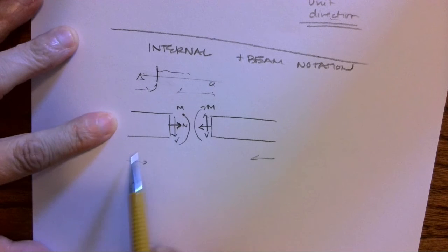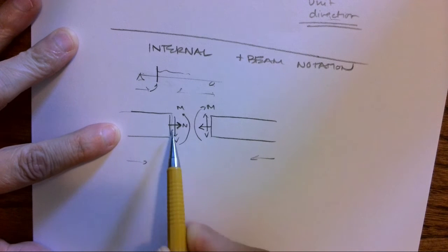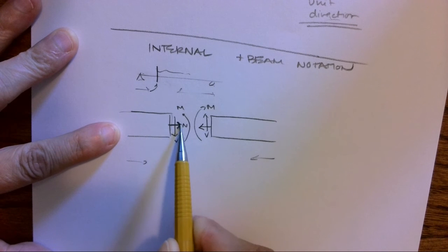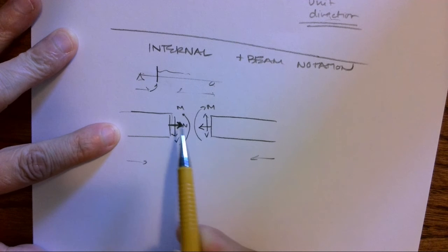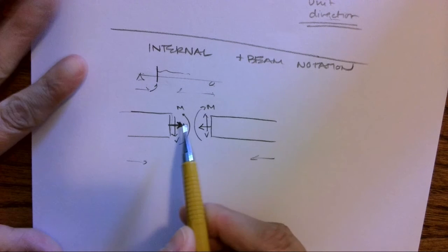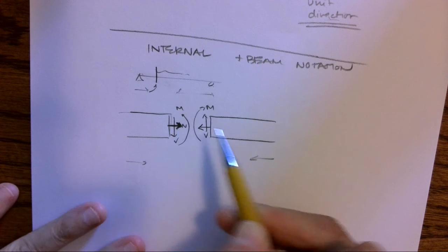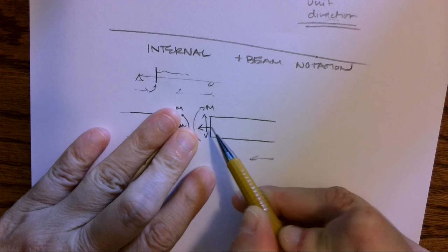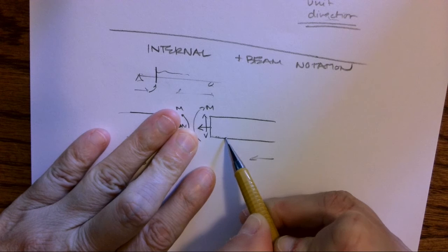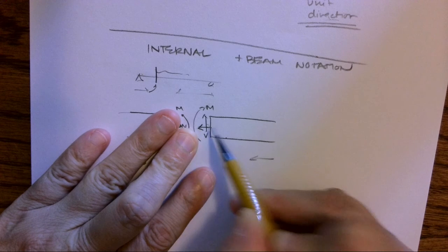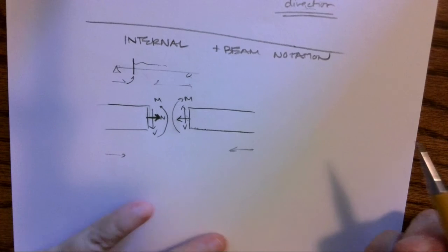If I'm coming from left to right for my solution set, and I assume that my normal is in tension, and I get a value that's positive that tells me it's in tension, and I draw an arrow to the right, well, how do I know that you're not drawing that arrow to the right on this right side? Because that would indicate pushing, compression. So that's why we talk behavior.